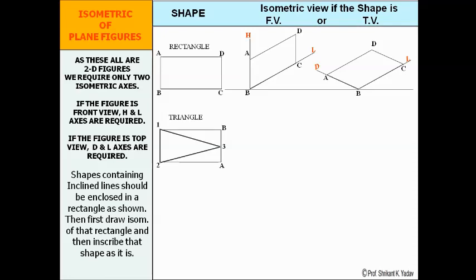Now to transfer this rectangle, first we will draw the reference line, and then we will create a vertical isometric plane by drawing the axes L and H. Here axis L makes a 30 degree angle with the reference axis, and H is the vertical axis, and both axes meet at a reference point O. Now first we will transfer the rectangle on the isometric plane, and for transferring the rectangle we will consider point 2 as a reference point, which lies at the intersection of both axes.